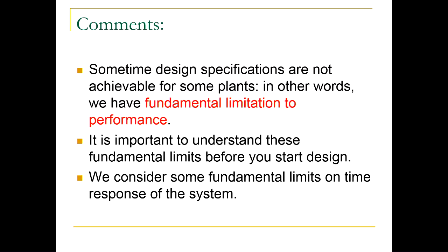Another thing which is perhaps surprising, and we never talked about zeros, but it turns out that unstable zeros can cause a lot of problems. Actually, zeros in general would constrain what you can do. We'll present some examples and then some results that summarize the effects of zeros in some specific situations. Often people ask me, well, I don't have to care about zeros then? Well, you do when you design, because zeros, unstable zeros in particular, might pose fundamental limits to what you can achieve in terms of design.